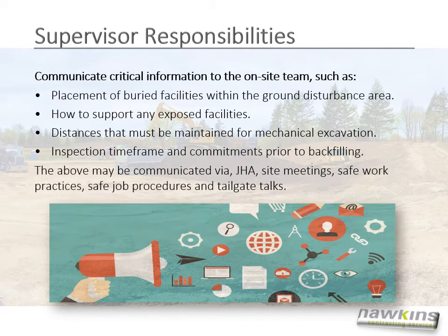Supervisors also have a duty to communicate critical information to the on-site team, such as placement of buried facilities within the ground disturbance area, how to support any exposed facilities, distances that must be maintained for mechanical excavation, inspection time frame and commitments prior to backfilling. The above may be communicated via your job hazard analysis, site meetings, safe work practices, safe job procedures, and tailgate talks. All communication methods must be exhausted to make sure you get it right.